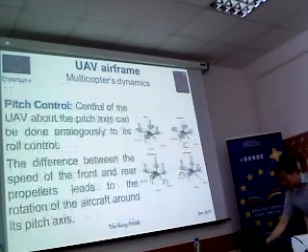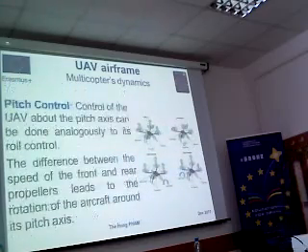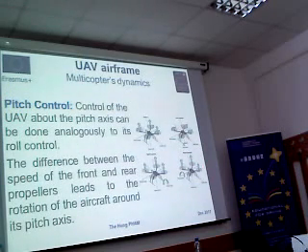And for the pitch, we have the same principle. The four rotors will be split into two parts, the front and the rear. When we want to make the rotation with respect to the pitch axis, we will decrease the speed of these two at the rear, and we will increase the speed of these two at the front.